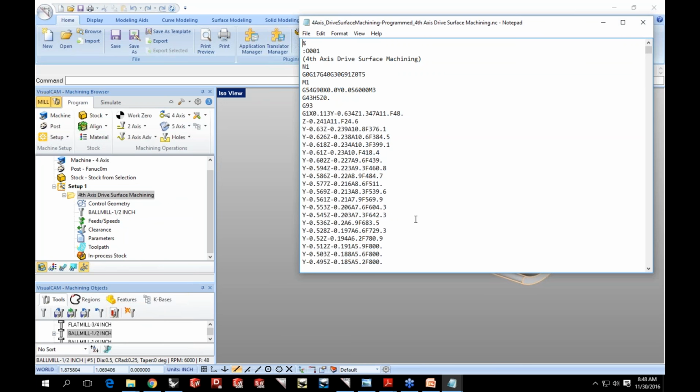So there's your inverse time feed rate, and this option is available starting with the expert configuration. The inverse time feed rates apply to multi-axis toolpaths, which is 4 and 5-axis toolpaths. So starting with the expert configuration where you have 4-axis toolpaths, you can take advantage of inverse time feed rates if your machine and controller supports inverse time feed rates.